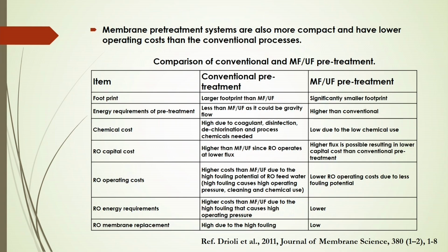And the energy requirement of the pre-treatment itself is less for conventional treatment, as it could be gravity flow, whereas energy requirements will be higher in microfiltration or ultrafiltration treatment because of the high resistance to flow through the membrane.